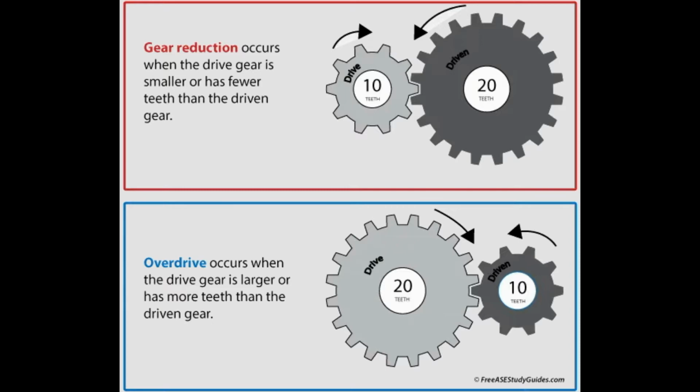When it comes to automatic or epicyclic transmission, the ratio of the locked annular gear to the planetary and sun gear gives the high torque ratios to the final drive of the vehicle, and the ratio of the locked sun gear to the planetary and annular gears gives the high speed ratios to the vehicle.